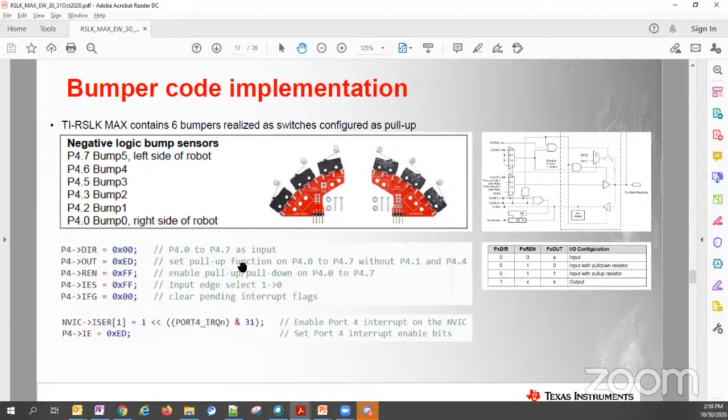The pull-up function ensures that your input pin is not going to float. It is at a steady, stable condition, 5 volt in this case, and just waits for a switch to pull the 5 volt down to ground. And no overcurrent will appear because there is an internal resistor that restricts high currents.